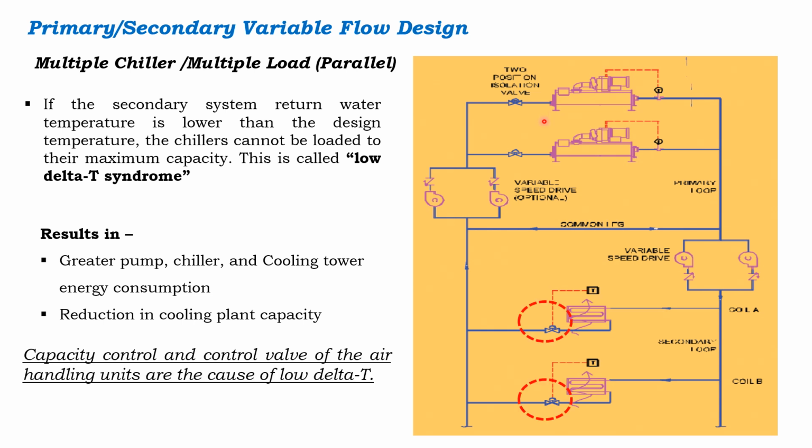So the capacity control valves are the reason for such issues. If they are not properly designed, the flow from the capacity control valves is going to be a problem. Today the pressure independent balancing valves, or the energy valves, are much more popular in the market. I will make a separate video for selection of the PIBC valve or the capacity control valves. I have already advised: for the low pressure drop conditions in the decoupler line, swing check valves are the best option to avoid such issues.